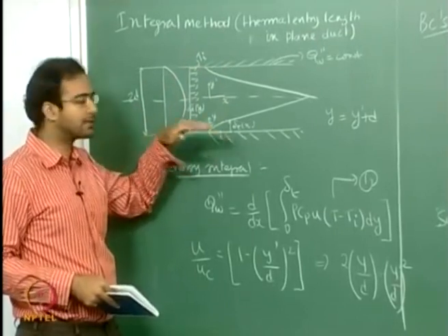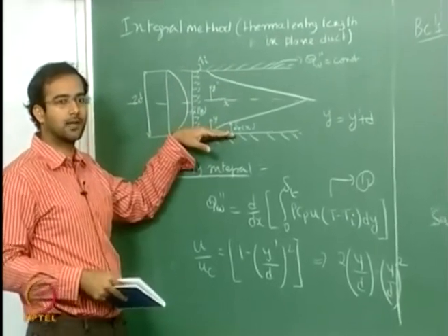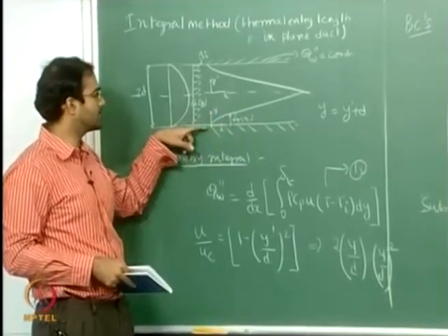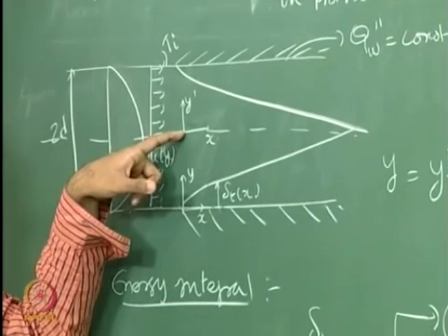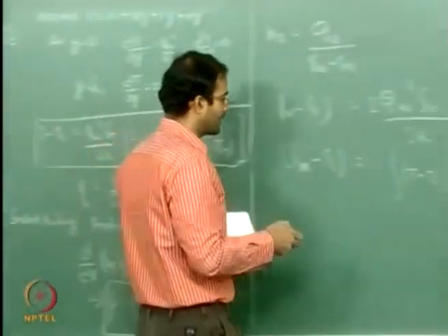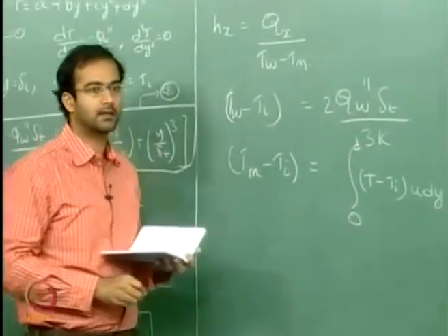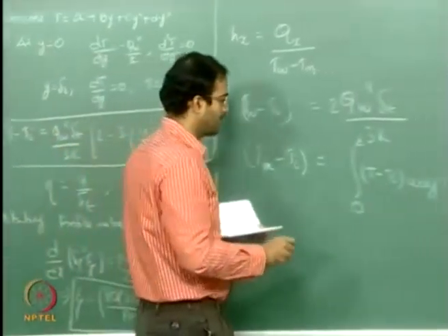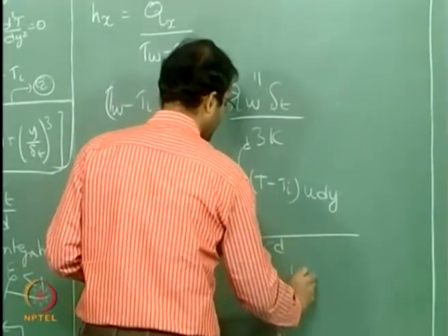Okay, now we are focusing on only one plate at a time. So for this, the velocity profile we have to consider is from 0 to d, where you have your velocity profile, that is the maximum velocity there. Alright, so therefore we will do this integration from 0 to d, because this is a mass weighted average we are taking, and divided by 0 to d u dy.